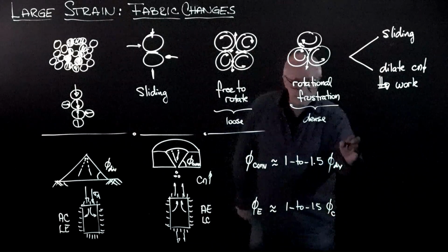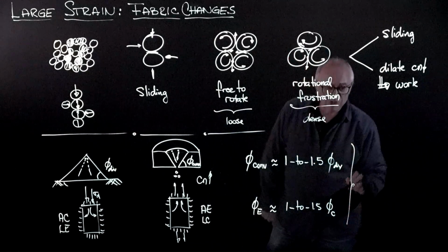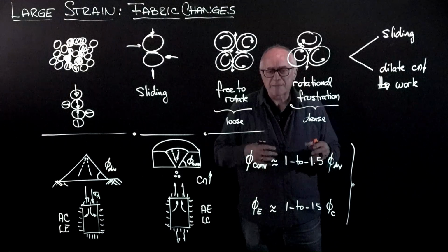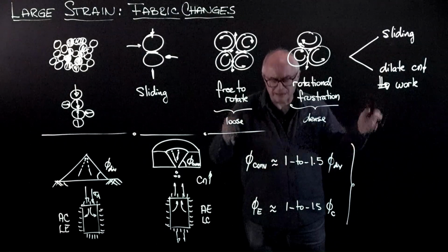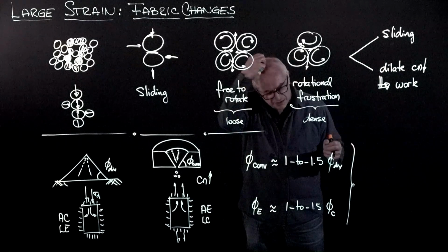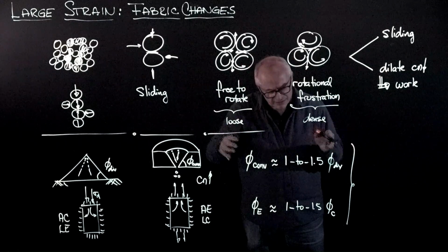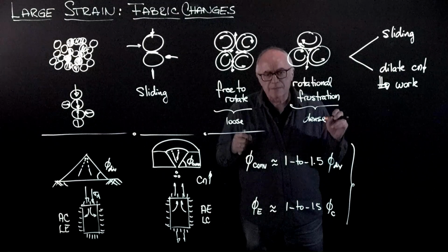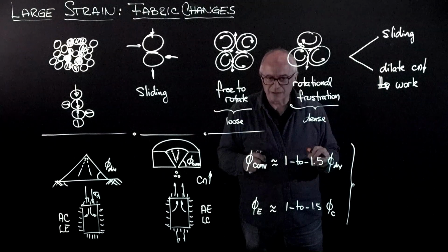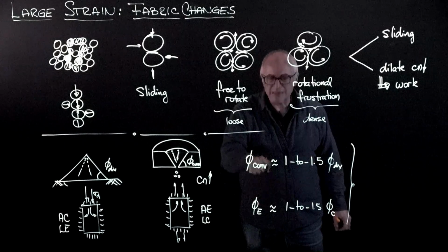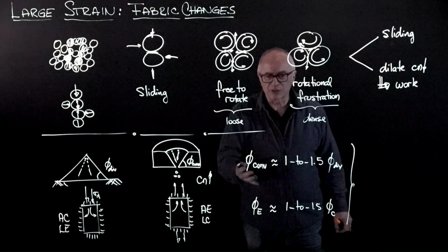Now, the implications are huge because if you remember, for example, the coefficients for the bearing capacity equations, Meyerhof, Prandtl's equations, the Nq and Ngamma, even the factor for Nc, they are logarithmic with the friction angle. And it's not that we're going to miss the friction angle by 1 or 2 degrees.